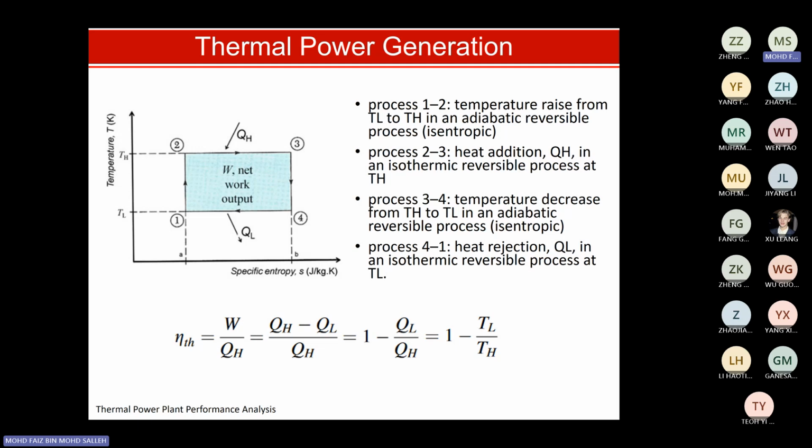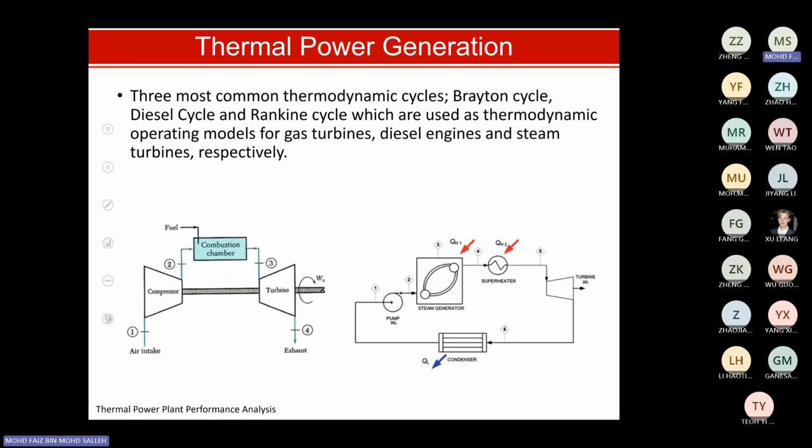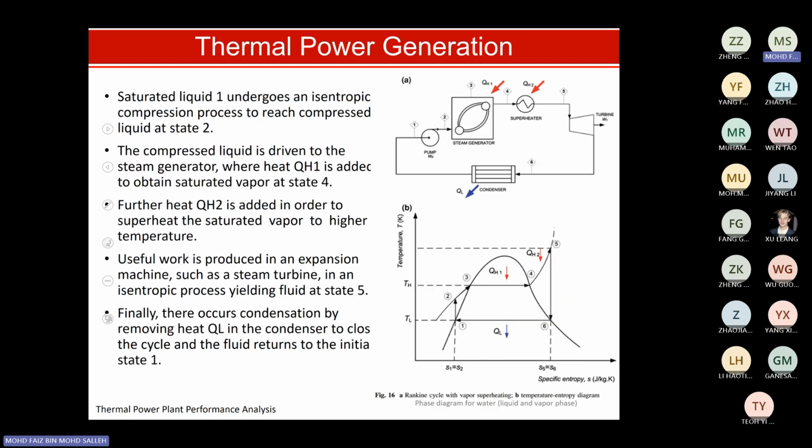Same goes in the thermal power plant. You need to cool down the steam so that it becomes water, but it doesn't go below 0 degrees, right? So if you can keep a big temperature difference and a high energy input, you can have a higher efficiency. And then we also discussed the Rankine cycle, which is usually used for the generation of electricity by the thermal power plant.